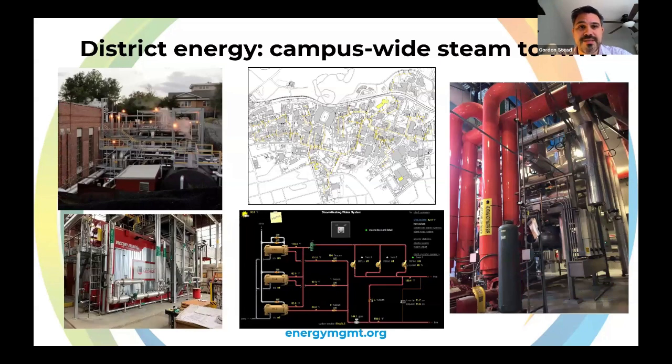So yeah, not easy to access, but then you get the steam traps and the trenches along the way. As anyone else who works with steam will know, on certain days you go around campus and you just see the steam plumes coming up out of the ground, and you can map out pretty clearly where the steam line is going. What also is fascinating is every year we get a drone flight with thermal imaging done at night, to see the map of the steam line underneath and to track leaks, which we get along the way. It's fascinating to see.